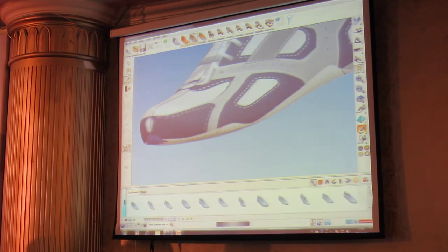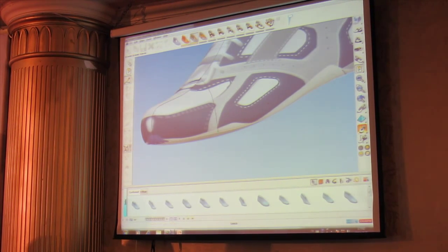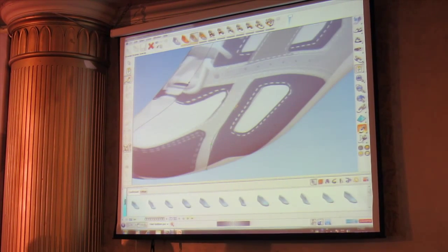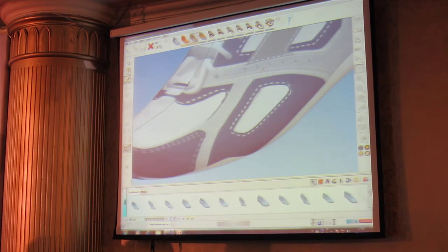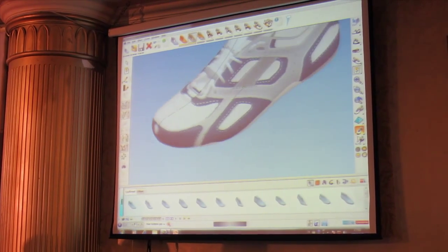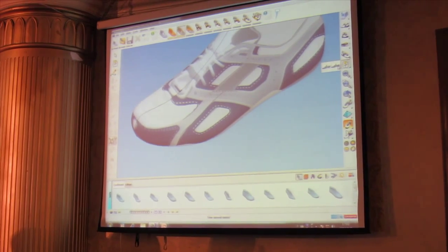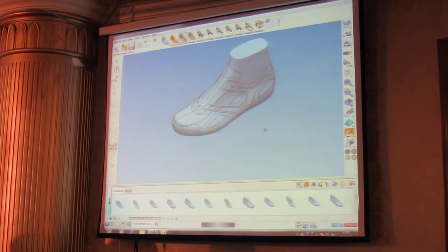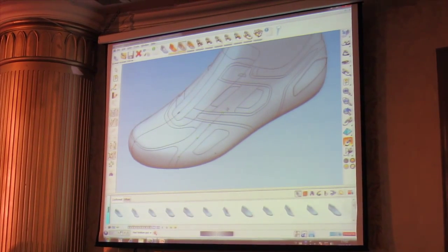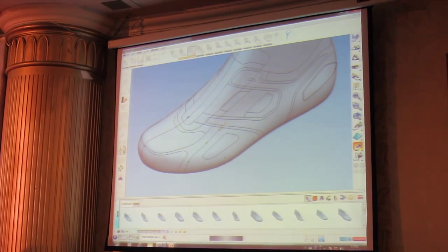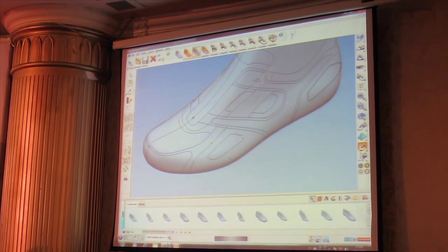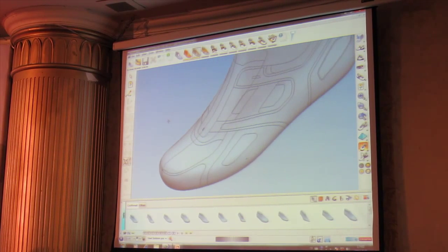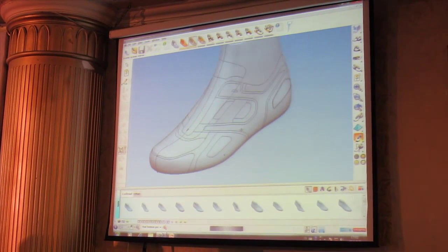Okay, so we can snap straight onto the feather edge, and the cursor turns blue when we close down on the feather edge itself, indicating that we're touching on the feather edge. Okay, let me just turn off the sketch for a moment, and I'll draw the other style lines. All the other style lines needed for this design I've actually got stored on another level because we don't have time to create all of these in the demonstration. So there's all the style curves that I need to create my complex design.